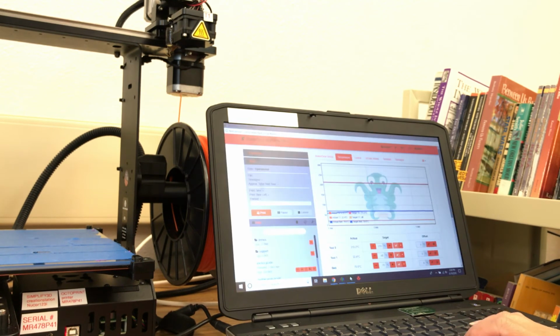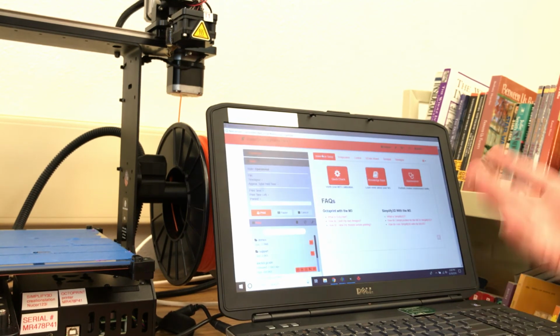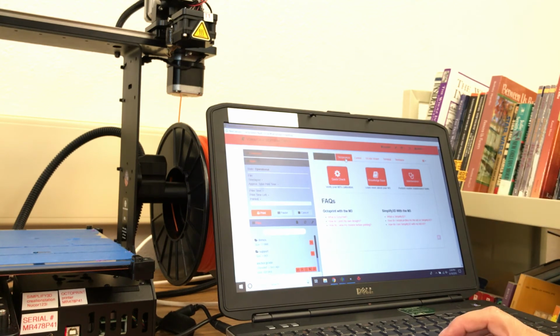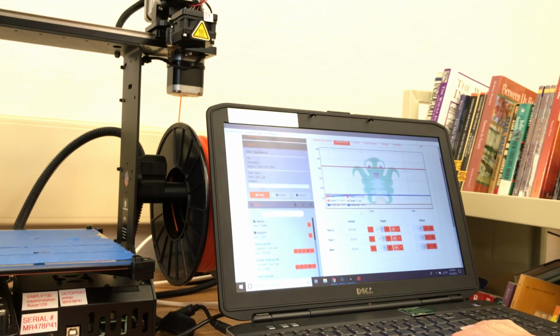And so I'll come down here. First thing you want to do, this is the default where it opens, you want to come over to the temperature button and you want to tell it to start heating whatever tool or tools you need. And if there's any question in your mind, you just click on the pull down, and again, we're using PLA, so you want to set it to 215. It's just a default. That's pretty easy.